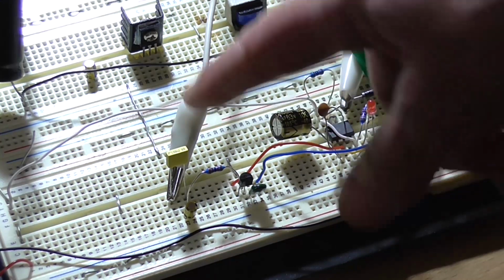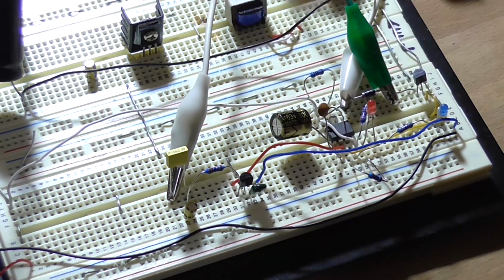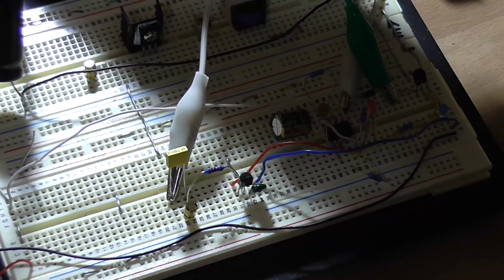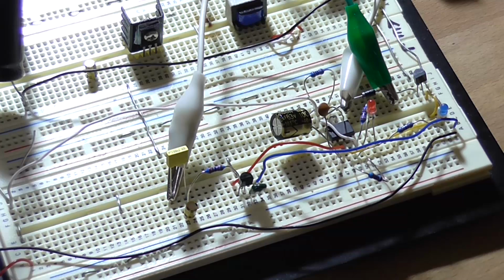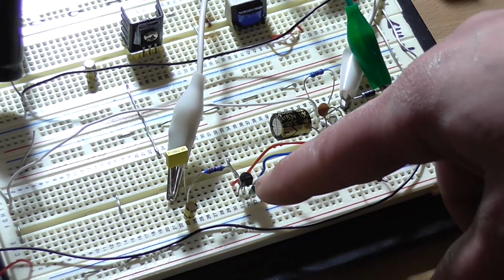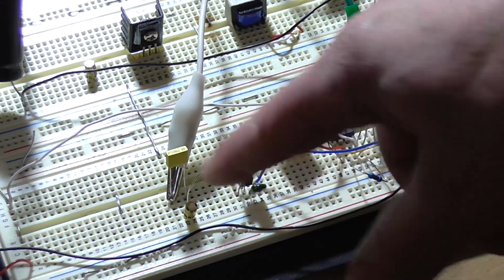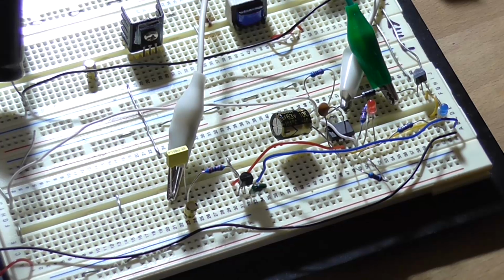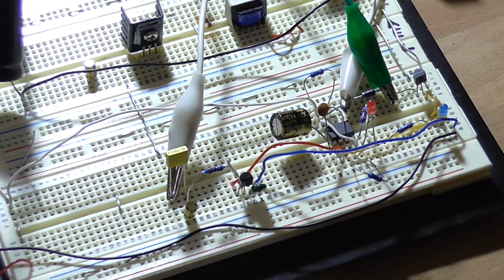I've got my oscillator from the oscilloscope going through my attenuator, which I'll make sure is turned all the way down, off of the output of the oscilloscope's generator, and I'm set to roughly 100 Hertz because I'm not really sure of what the frequency response of this low pass filter is, where it starts to roll off. So I'll set it at 100 Hertz. It'll probably work at kilohertz, but anyway, I'll turn the circuit on.